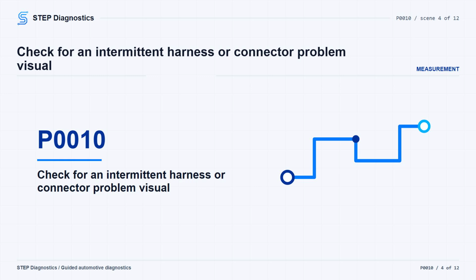If it stays under the limit, reproduce the operating conditions for the code, and if available, reproduce the captured conditions from the failure data. If P0010 sets again, continue into circuit testing. If it does not set, the system checks OK at that time.